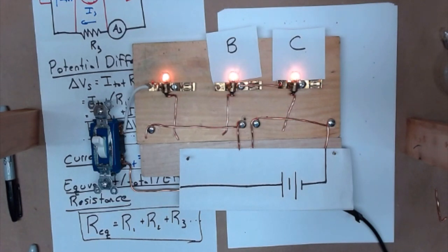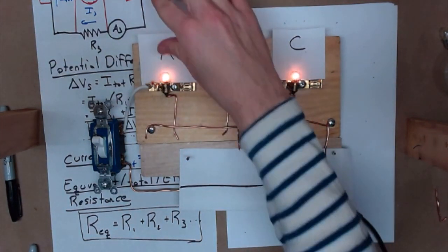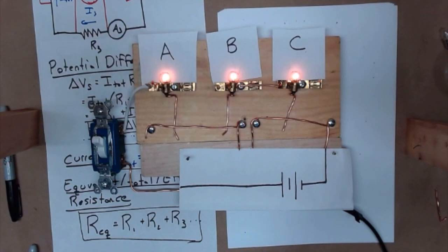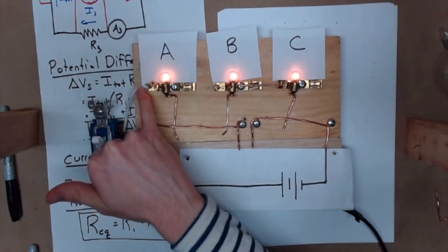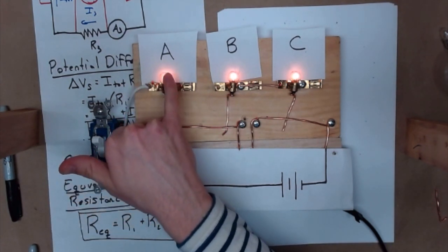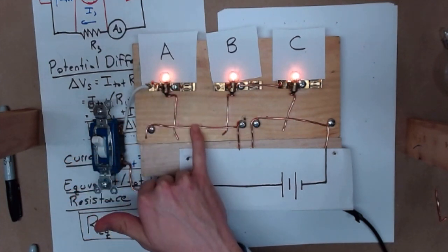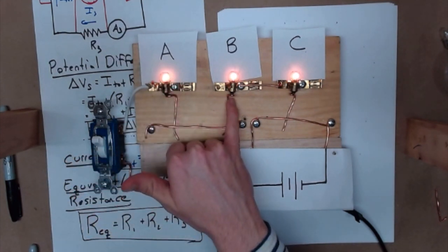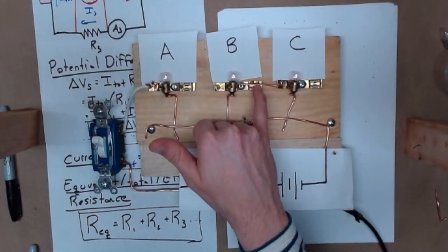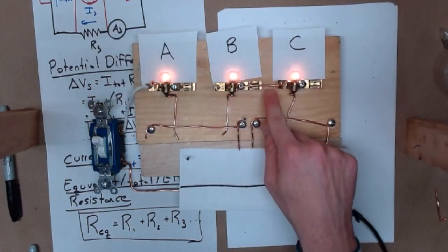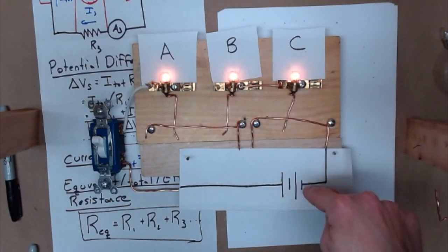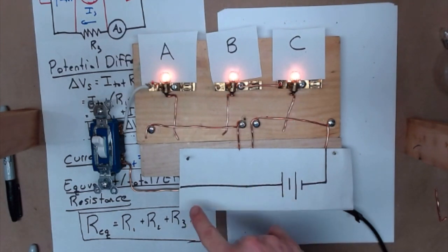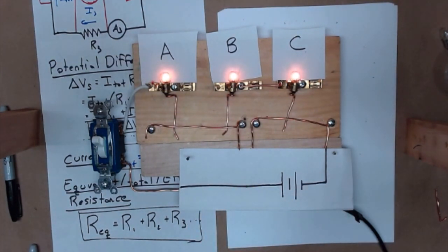Okay, so I have my 3 bulbs illuminated, A, B, and C. Now, following the current out of the high potential through the wire to the switch, around to here, high potential still here, through that casing, through the filament, down through the copper, over to here, up through the copper, through the bottom, through the filament, through the side, over, through the side, up through the filament, down through the bottom, through the copper, over to the negative. So we see we have a complete closed circuit because the battery is connected high to low potential.